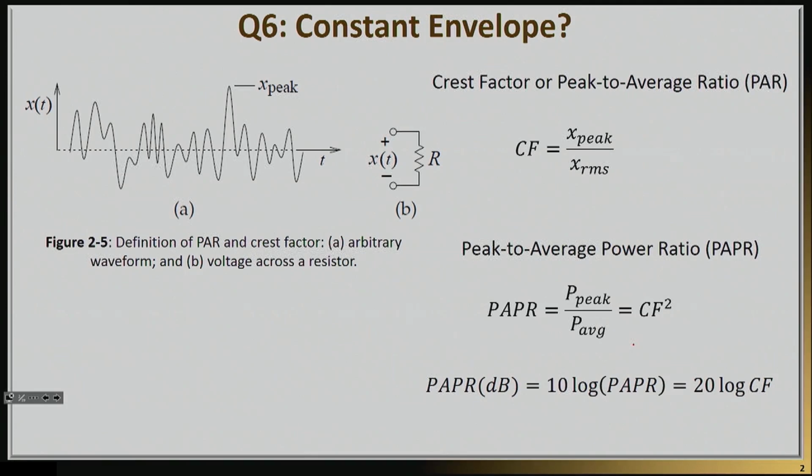First of all, there are ways you can quantify this. You can clearly see here there is something called the crest factor that we can define. It's a very simple idea. You're comparing the peak signal, which you can see here, to the RMS value of your signal. So some people will quantify this variation with a crest factor.